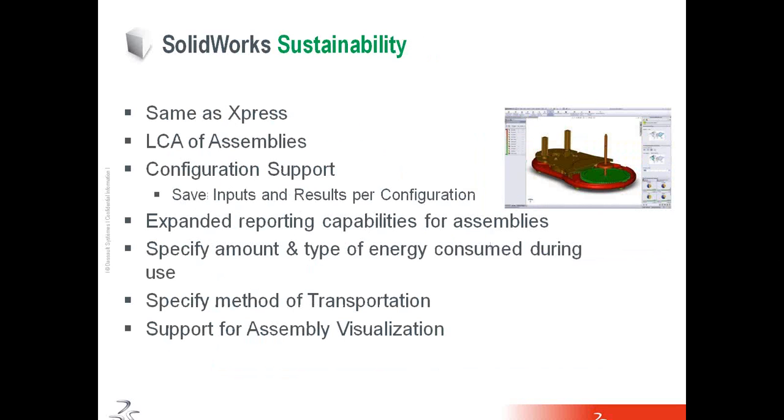And the second product is called SolidWorks Sustainability. It is a full blown out product from SolidWorks, and the capabilities are the same as Express, but apart from that, you can also do the life cycle analysis of assemblies. It also supports configuration. So let's say if you have 3 or 4 configurations in your assemblies or parts, you can save different set of inputs and outputs for each configuration. Also, it has some expanded reporting capabilities for assemblies.